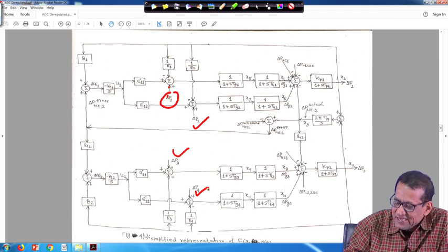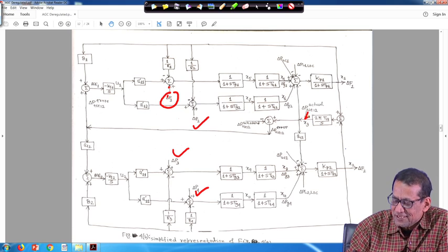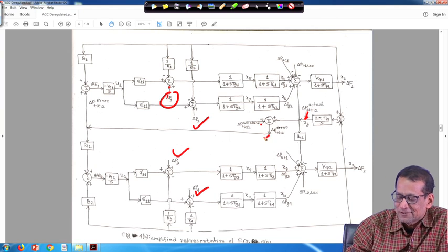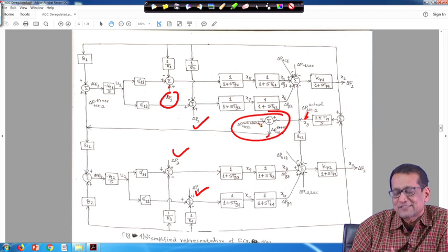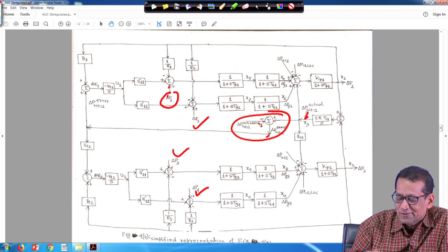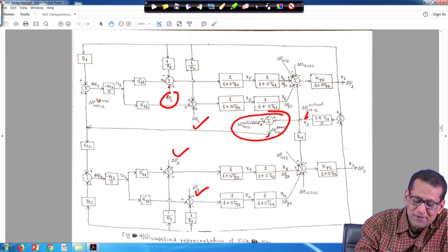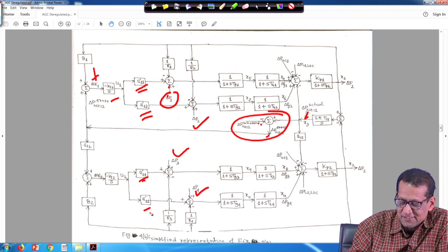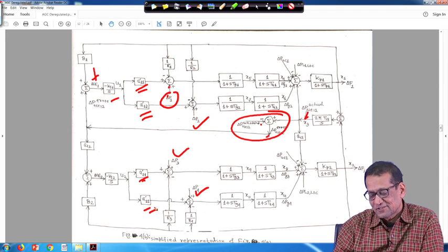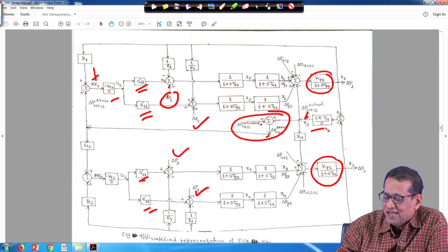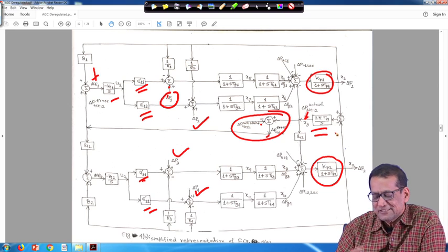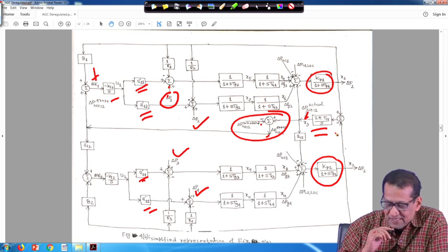And then in this area, this is the actual and this is your delta P tie 1. So, actual minus schedule is equal to delta P tie 1 error. Here also, from the previous block diagram we have drawn this simplified version, such that it will be easy for realization. So, this is your delta P tie 1 error. Finally, this is ACE 1, integral u 1, and I told you this is the AC participation factor, this is also an AC participation factor, right. This is power system 1, that is area 1 and area 2, and this is, as usual, the actual tie line power flow, right. This we have already seen for the conventional case, right.